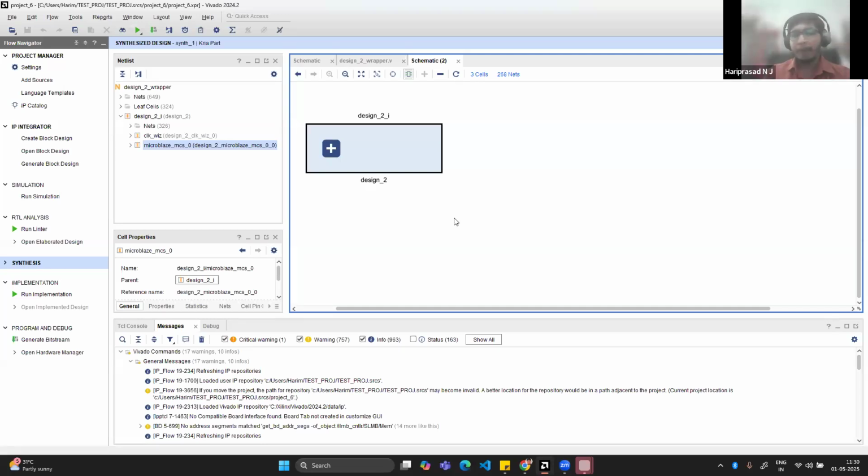If you map them into IOs, that takes thousands of pins, like 8-bit, 8-bit, and I'm trying to decompose a 1024 by 1024 matrix. If I just put that matrix multiplication algorithm inside the FPGA and synthesize, it will just trim off, and there is no significance to it at all. Many a time we make that mistake, synthesizing and seeing how much resource is utilized. That is not the right way.